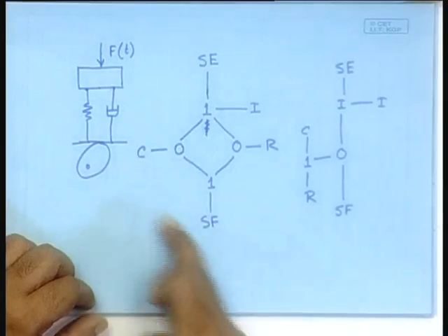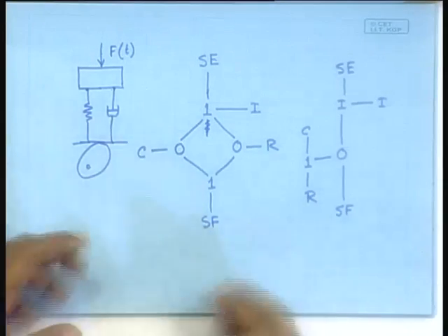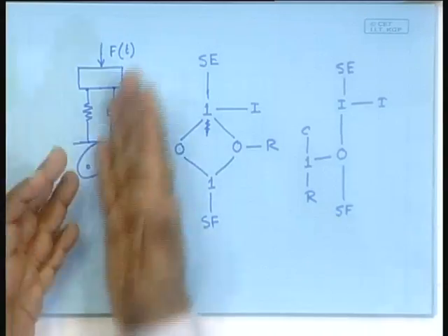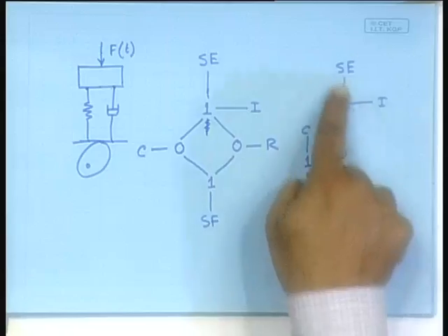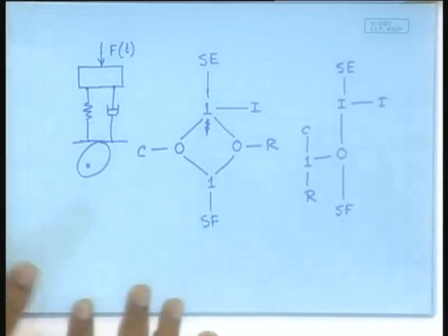We need to ensure that this graphical structure contains the complete information about the exchange of the flow and effort. As it does not, we need to do something more to it, but nevertheless the concept is that any system will be converted into a graph like this. These bonds will tell how the effort and flow informations are shared between different elements.